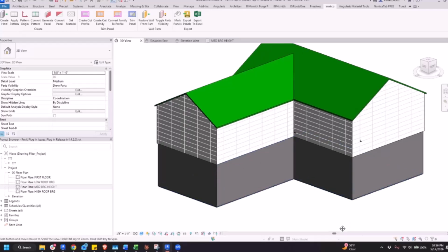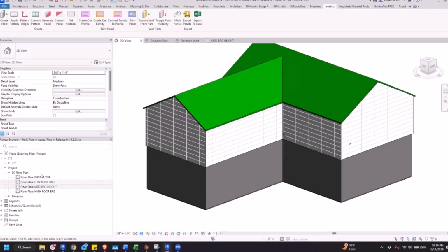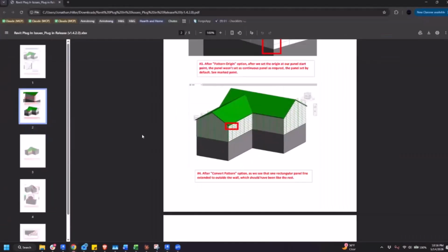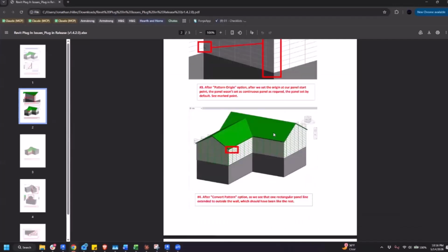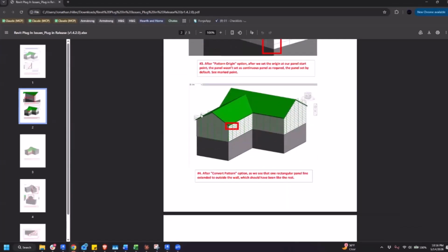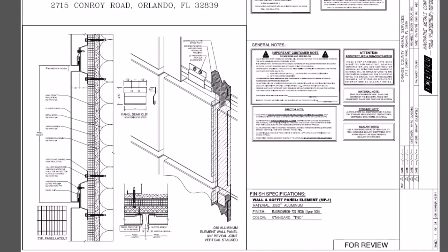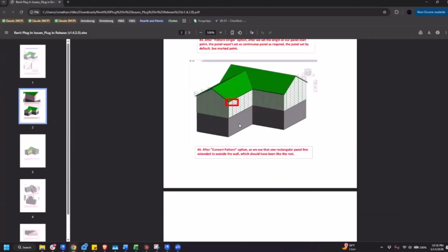What we discovered is that it isn't completely perfect. Unfortunately, it cannot do it that way. I think you guys know how this works in Revit: when the cutting or the trimming is overlapping things that should not be cut, or the lines are way too close over the edges of geometry, there's an error. And that's what happened in this case. The automatic layout that it created for the wall was trying to trim an edge of a wall on panels where the geometry was too close. So instead of cutting it, it just stopped. It was an error.